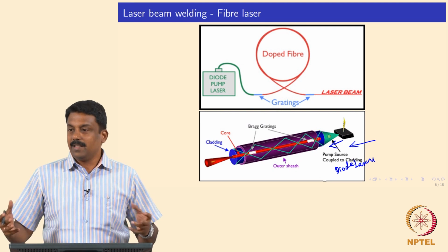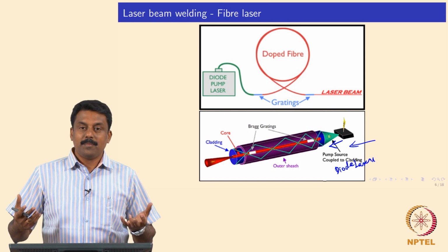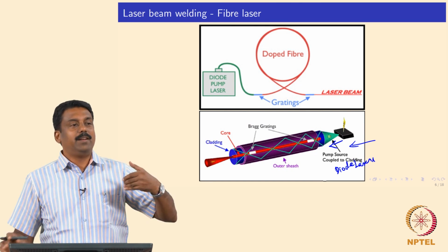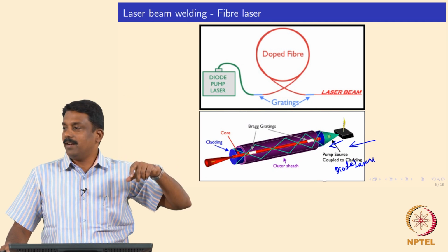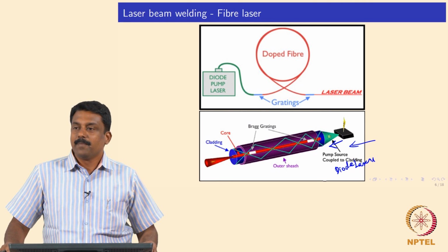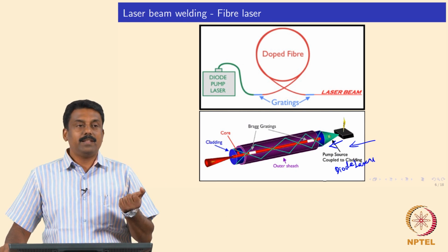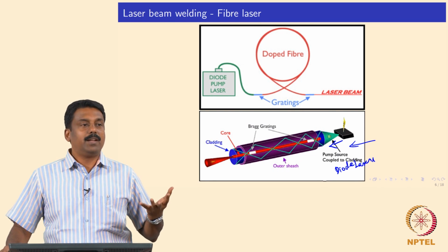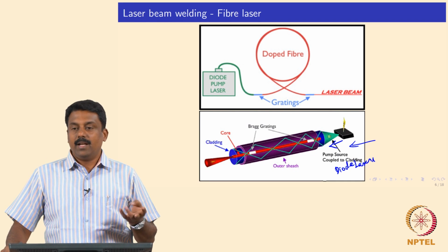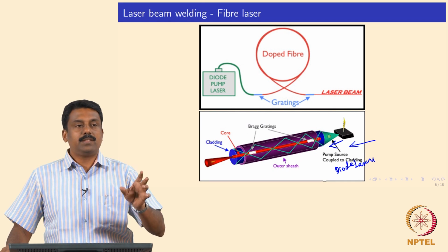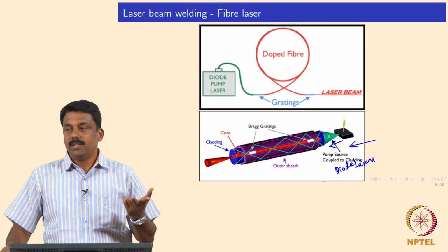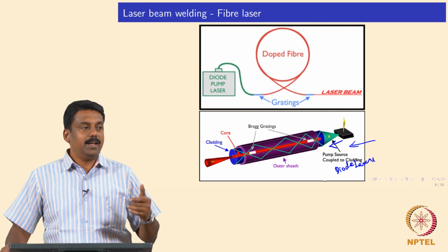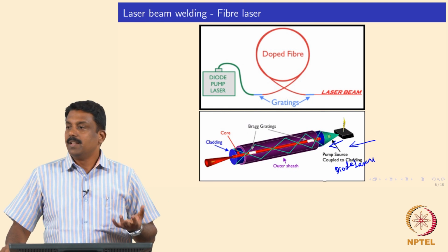So, you can get the fibers, and it is very flexible, right. You can also manipulate it, and you can keep the lasers somewhere else and then get it delivered. And in an Nd-YAG system, the Nd-YAG system itself is huge. Okay. If you look at a 4 kilowatt Nd-YAG, each Nd-YAG crystal can be made into 200 watt rods, and it also needs a pumping source.